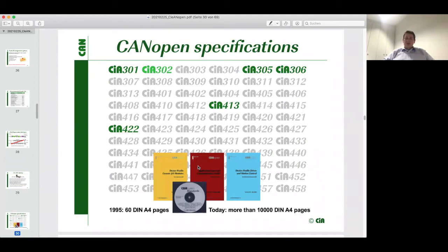Well, how are CANopen and CleANopen related to each other? CANopen is not a single monolithic document, but consists of an entire profile family. The basic functions of CANopen, the device architecture and the basic services, are provided in the document CiA 301, but we can differentiate between two document ranges: the documents in the range 300 and the documents in the range 400. In the range 300, we find the communication rules and extensions to the basic communication profile.